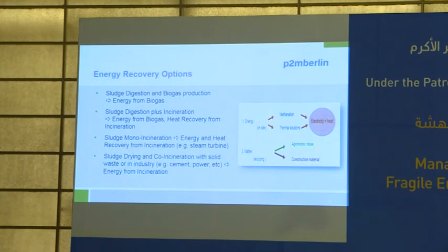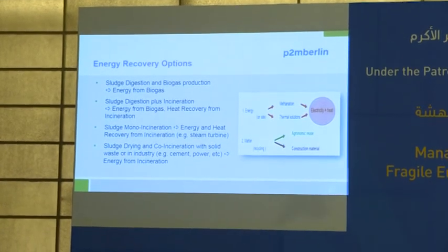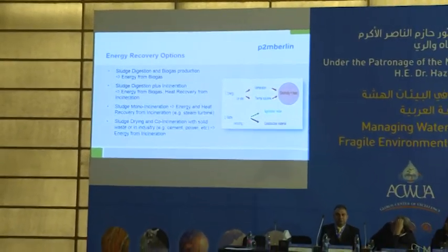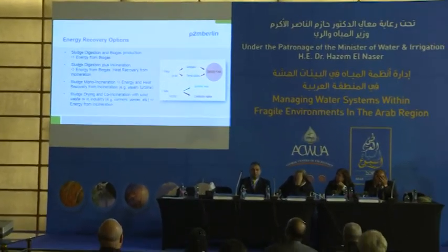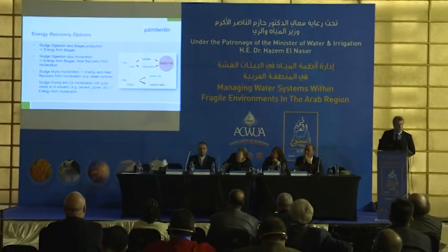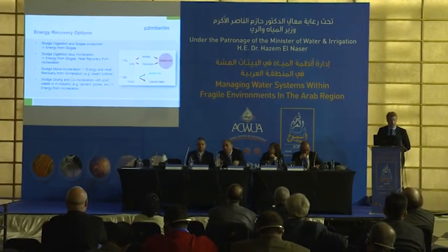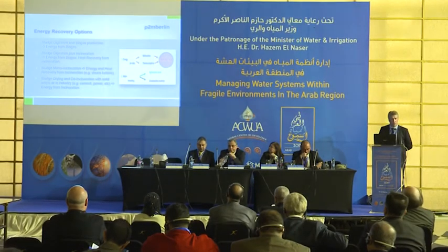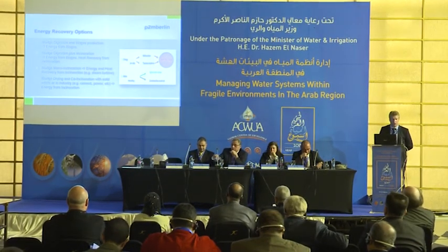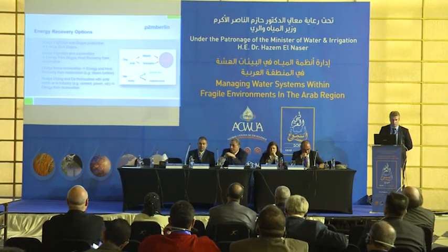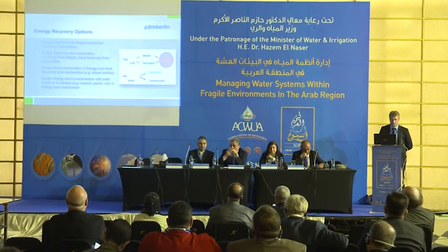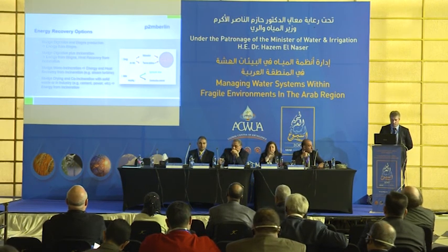Energy recovery, we heard about it. What are my options? One option you heard is biogas production. Digestion plus biogas production is a viable source of energy. Then you have the option of digestion plus incineration. Again, what is your end product? What do you need to dispose of at the end of the day? You can recover energy in the form of electricity and heat. We have mono-incineration. Again, you can recover heat and electricity. And then you have co-incineration with other wastes or in the cement industry, as we also heard already.